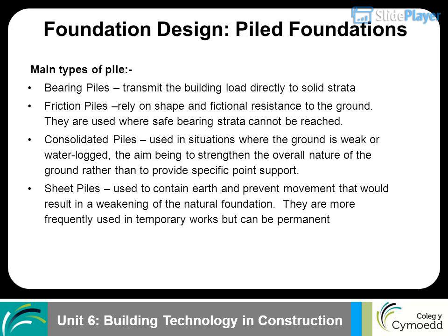Foundation design: piled foundations. Main types of pile. Bearing piles transmit the building load directly to solid strata. Friction piles rely on shape and frictional resistance to the ground. They are used where safe bearing strata cannot be reached.